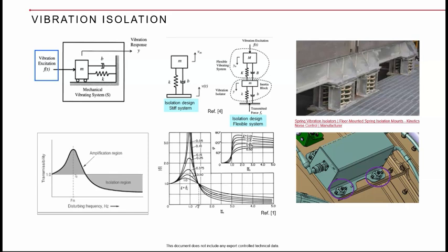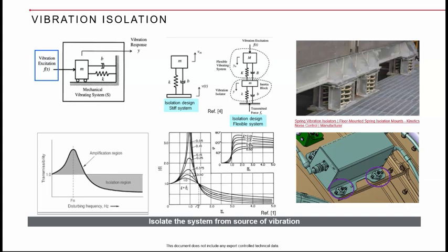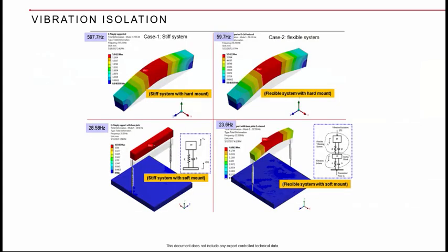Okay, that means this is going to be a rigid body and you are having a spring here. So with the isolated natural frequency at 1 by root 2 times the operating range, you can say that your amplification is never going to be more than 1. Okay. So you can appreciate that when you see this example here.